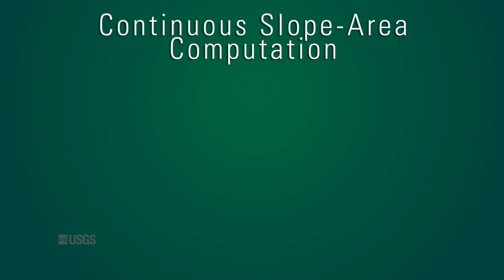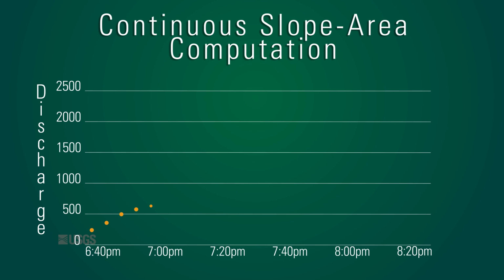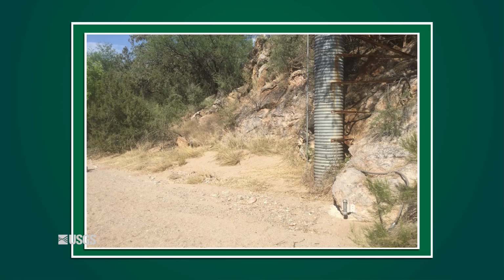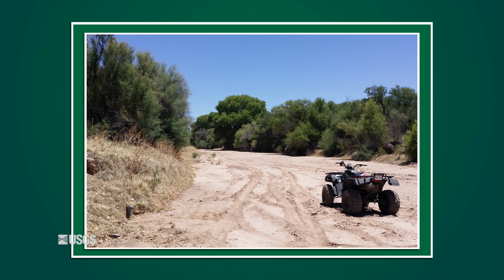What sets this apart from the slope area method is that the sensors measure the water surface of the stream reach at 5-minute intervals, allowing for a complete computation of the flood hydrograph. This method provides a safer alternative to direct discharge measurements while providing discharge data at stream gauges that are inaccessible or have no provisions for making flood measurements.